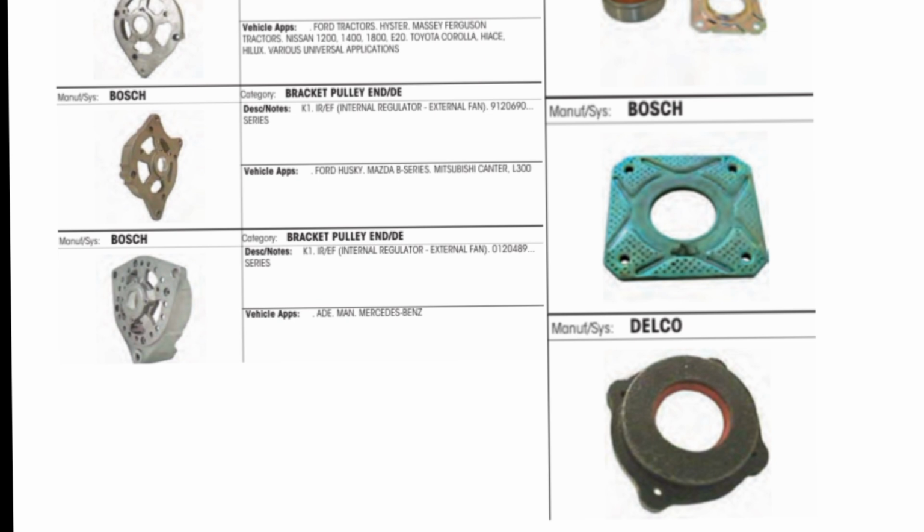Today we will discuss the alternator used in vehicles. An alternator works together with the battery to supply power when the vehicle is running. The output of an alternator is direct current, DC. When the alternator pulley is rotated, alternating current, AC, passes through a magnetic field, an electrical current is generated and converted to DC via the rectifier. The current is controlled through the voltage regulator in order to cope with the varying electrical vehicle loads.